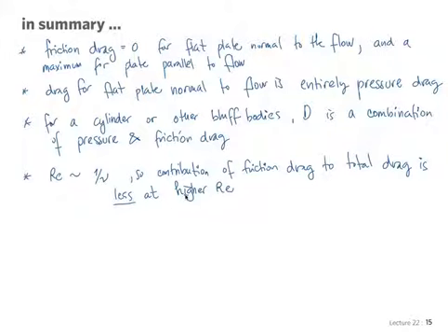Reynolds is proportional to? Yes, it varies as 1 over Reynolds, 1 over viscosity. And in the case of bluff bodies for large Reynolds numbers, the friction drag can mostly be neglected because it's going to be mostly pressure drag. If the Reynolds number is large, the viscosity is very small, and so friction drag contributes little.